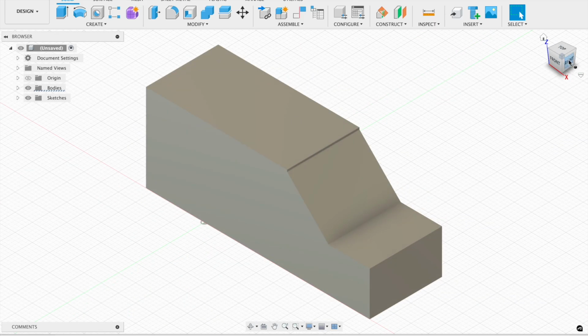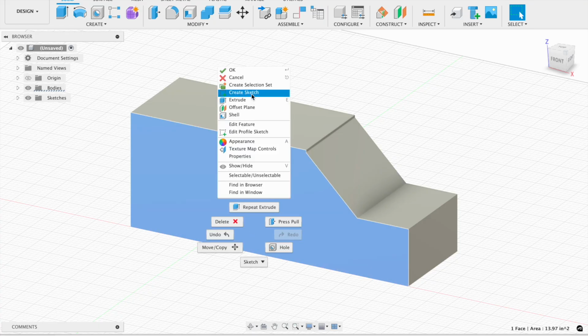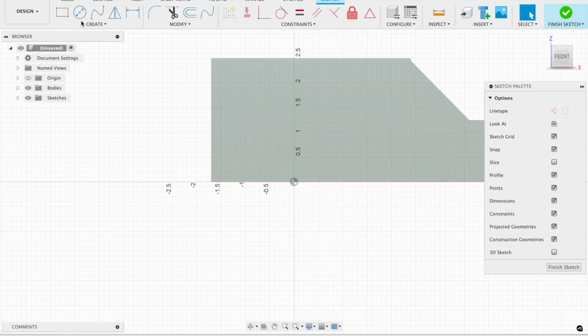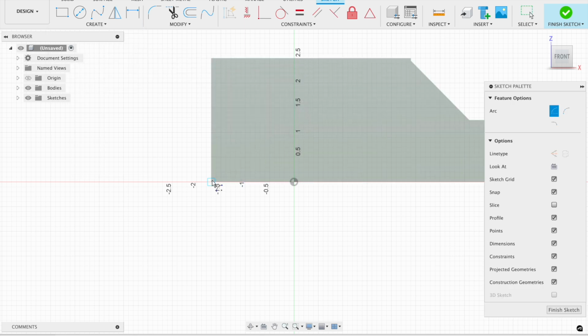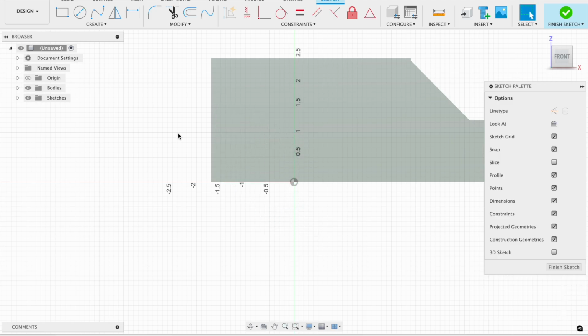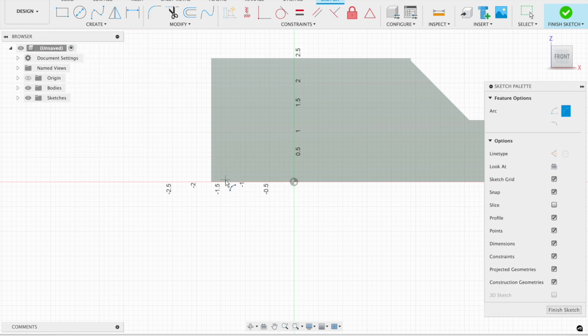So I'm going to highlight a very helpful sketch tool in this next clip, and that's called the mirror tool. What you will essentially need to do is make anything on one side and then set a line of mirroring, or an axis, and it will copy over exactly how it is on that side onto the other side. It's a really useful tool.